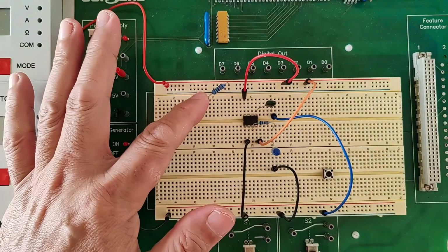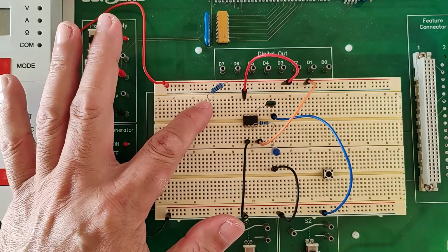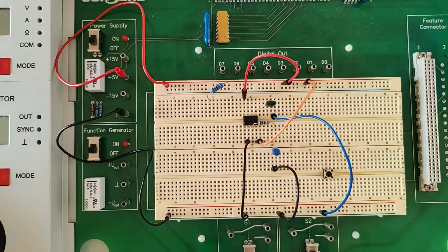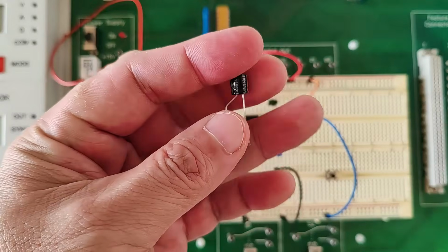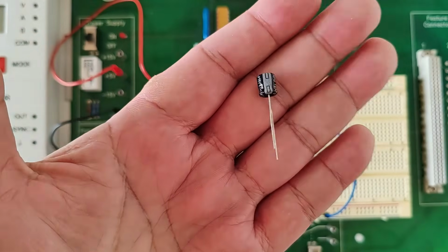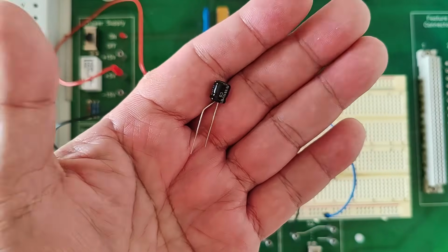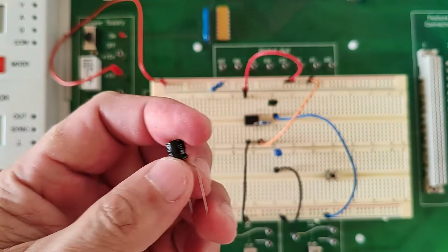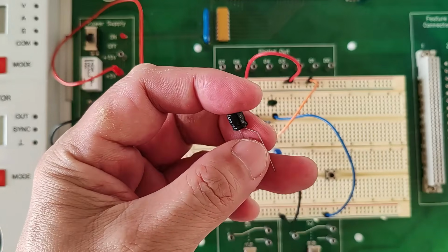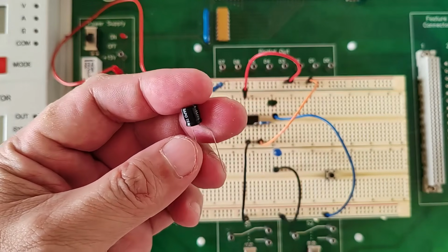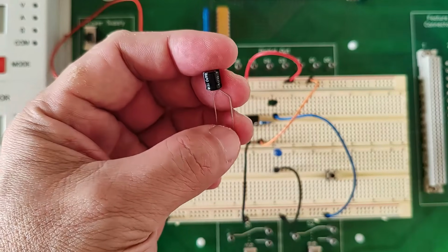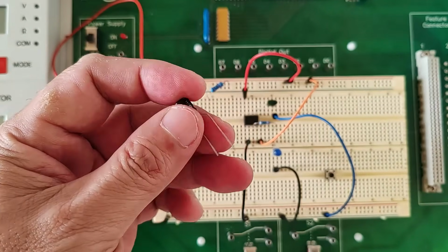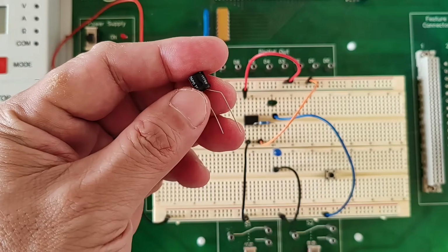There. 10 kilo ohm connected to 5 volts and the other leg to a free pin. Now, that other leg of that resistor, the 10 kilo ohm resistor in particular, will have to be connected to a capacitor. Based on the schematic, we're using a 47 microfarad capacitor for this purpose. Which leg of the capacitor, because there are 2 terminals of this capacitor, to be connected to the 10 kilo ohm resistor? I need to connect the longer leg, which is the positive leg of the capacitor. The negative leg of the capacitor will have to be grounded.